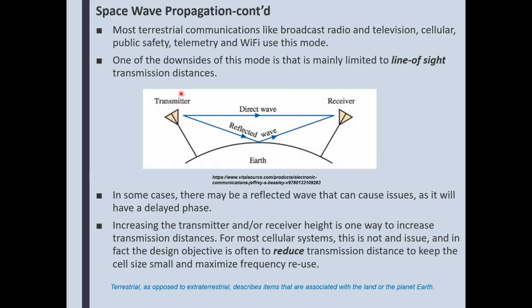All right. You see what happens here? The antenna transmits, it broadcasts the waves, and the waves are always going to hit the Earth here. And that is going to become a secondary isotropic point, and that thing is going to start transmitting. So there could be some issues due to the reflections. There could be some echoing because this distance is shorter than this total distance. For the most part, things are not happening with problems here.